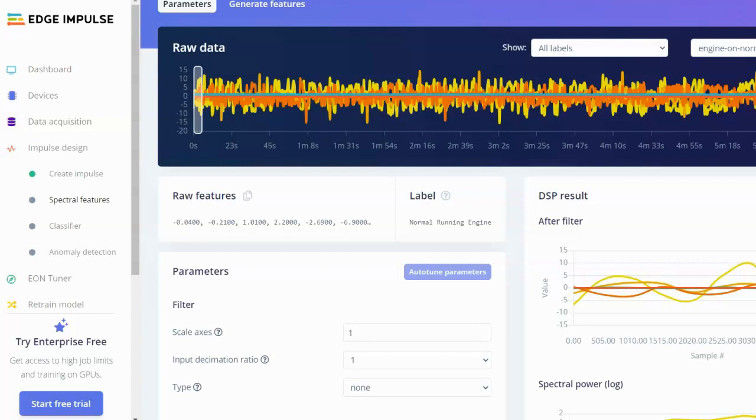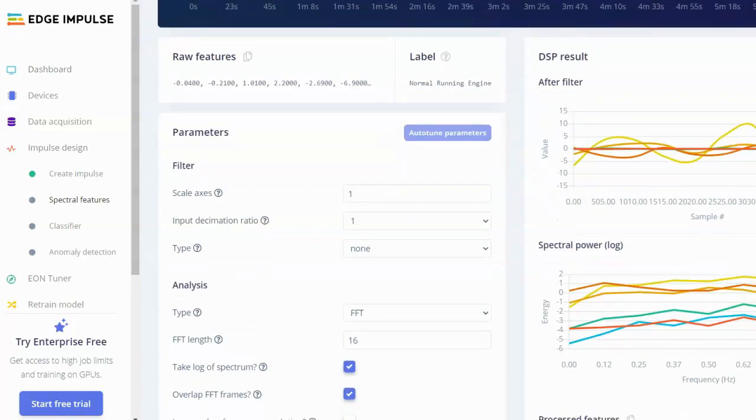These filters can be low pass, high pass, band pass, notch filters. Applying filters can really help remove the noise and isolate specific frequency components, and this is what we are really after, because when the engine is in a running state you can see that it is oscillating in a certain pattern, and when it's in an idle resting state it also has certain specific frequency parameters.